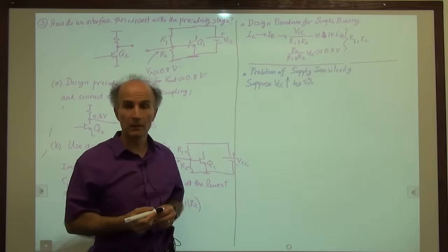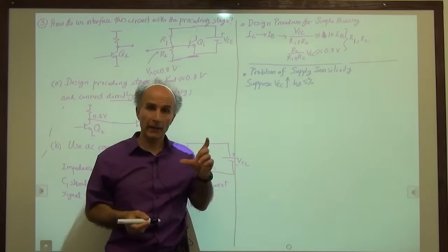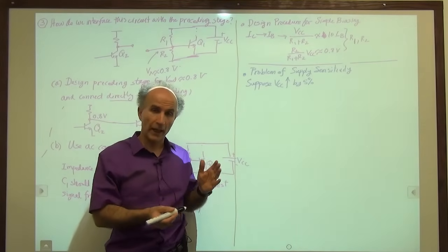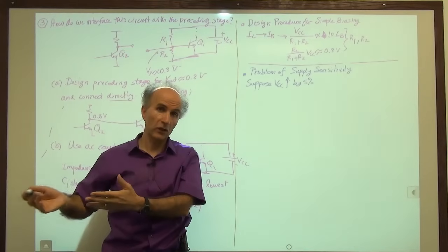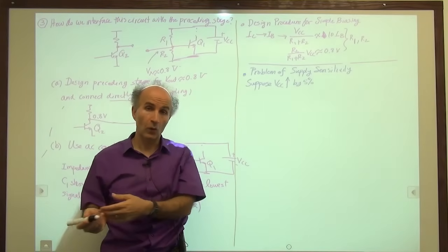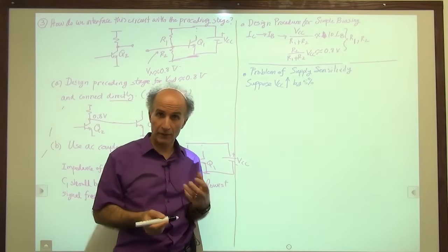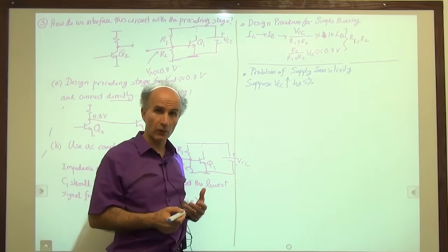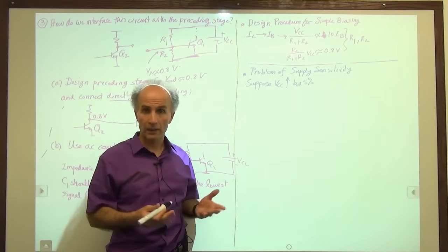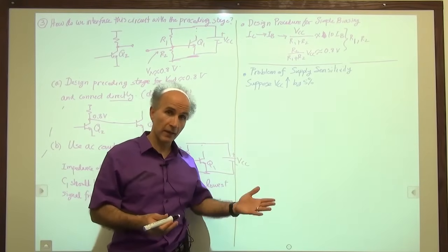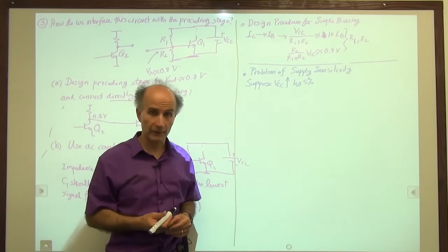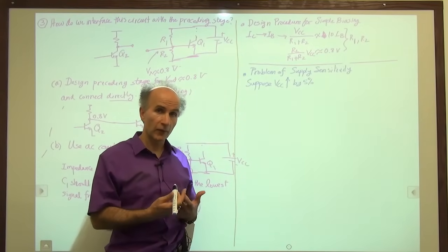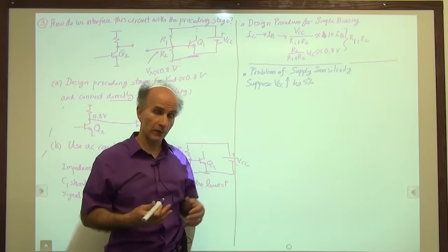Why should that be? Well, when you connect a battery to a system, it has a certain voltage, and when the battery ages, its voltage goes down. Or if you have a voltage regulator that is used to supply a voltage to a circuit, that has some tolerance. Sometimes it's higher than specified, sometimes lower than specified. So we have to be able to run our circuit from somewhat higher, somewhat lower supply voltages.